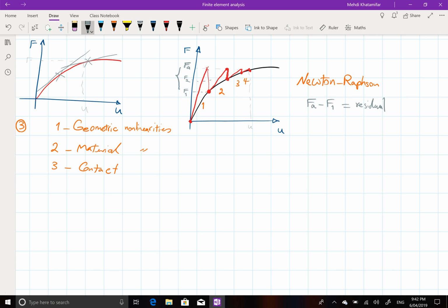It's not easy. You need to make sure your geometry is correct, your boundary conditions are correct, your mesh density is correct and fine enough, and also you need to check the number of sub-steps and maximum and minimum steps gradually to find it. And if it's not enough, you need to gradually decrease the number of steps to converge. Basically, it's about trial and error. When you get more experience or you have more training, that trial and error time is going to decrease.